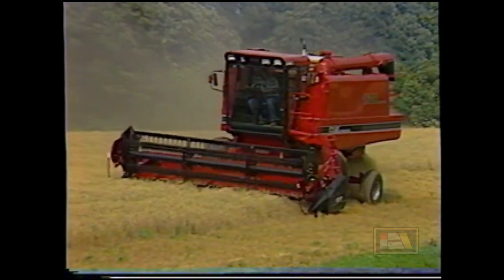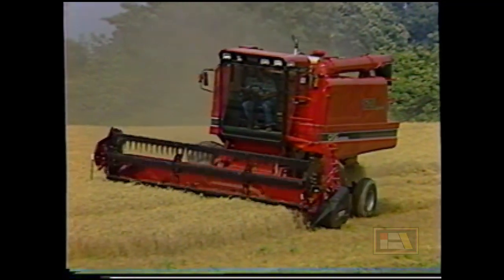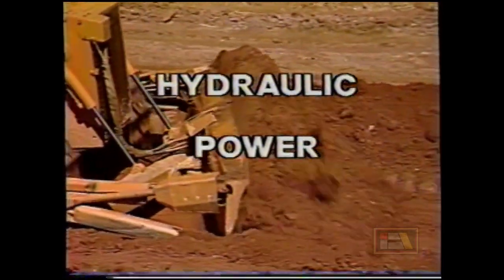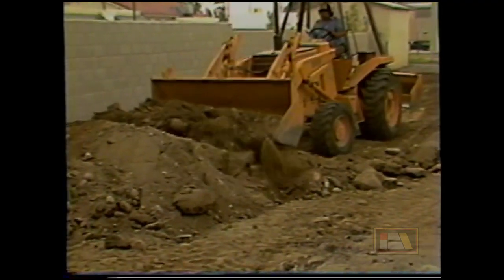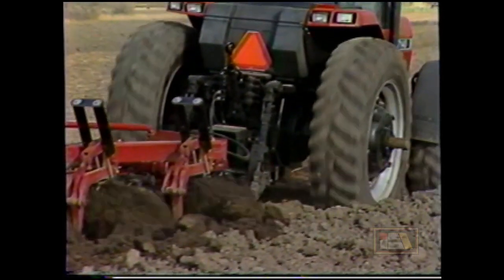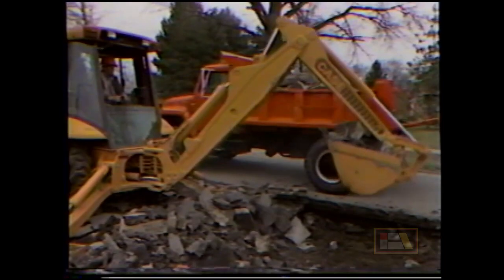To get started in understanding more about the hydrostatic systems in today's equipment, let's go over a few commonly used terms. First is hydraulic power. That is simply fluid power, which is transmitted through lines or hoses to a cylinder that converts it into a mechanical output capable of doing work on a load. You see examples of this all the time, like the lift cylinders on a loader, or the hitch lift cylinders on a tractor. Hydraulic systems have greater flexibility than mechanical and electrical systems and can produce proportionately more power than other systems of equal size.